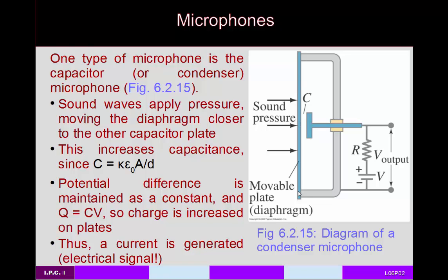There's some charge, therefore, on each of these two plates of the capacitor. And as you know, the capacitance is kappa, the dielectric constant for whatever's between the two plates, times epsilon naught, the permittivity of free space, times effectively the area of the capacitor divided by the distance between them. Now the area maybe is a little complex if you have two plates of different size, but you can still come up with something that represents the area term, and once you've calculated it, it's effectively constant.